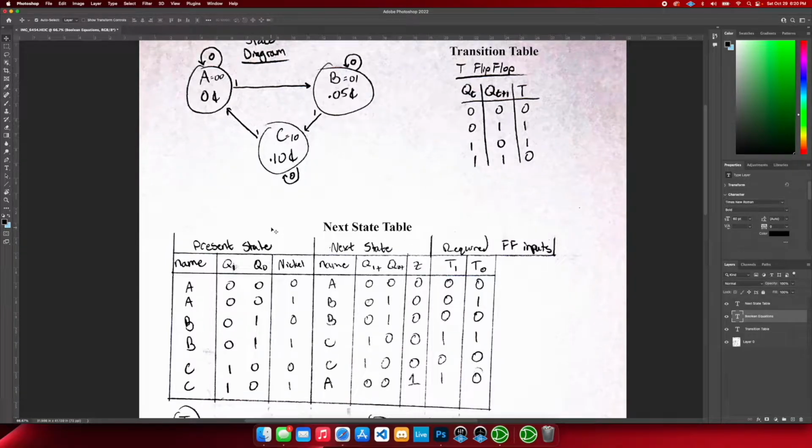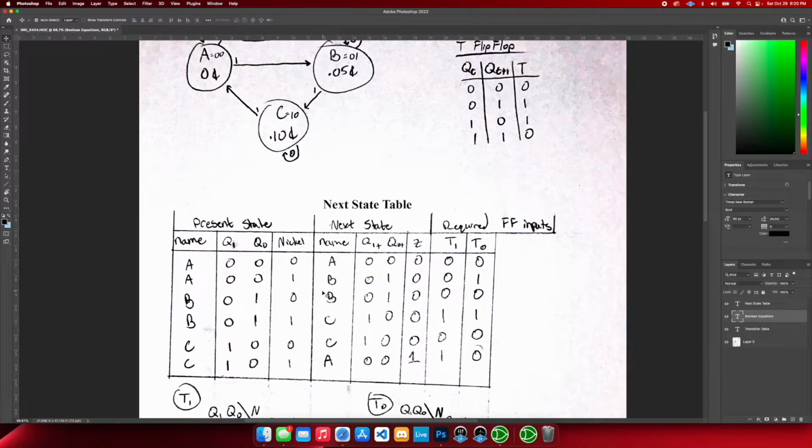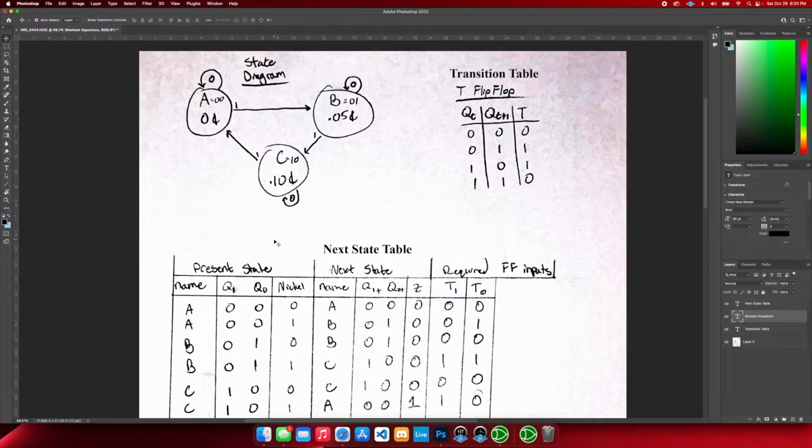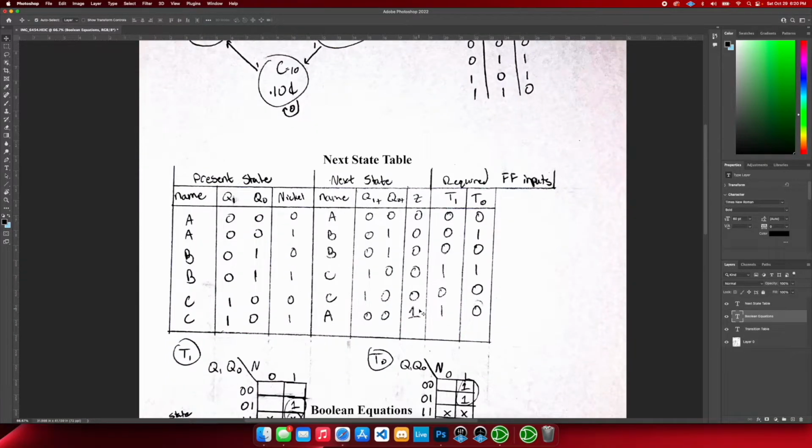All right. So here is the finished table. You could see that the next state is what happened when you put a nickel in to 0,0, it moves to the B state. This is the B state. And we're only going to have an output of a gumball, Z being our output. We're only going to have an output of a gumball when we reach the end of state C, putting in that nickel, and then going back to state A. That's how we get our gumball there, okay?